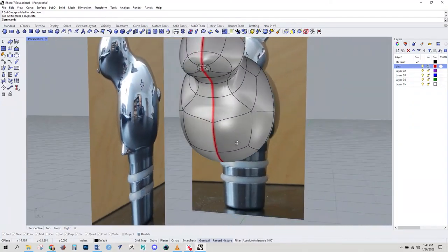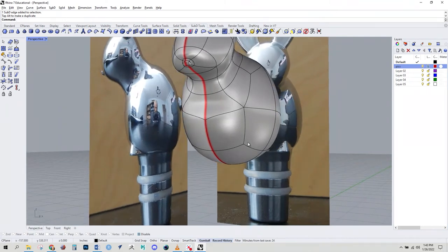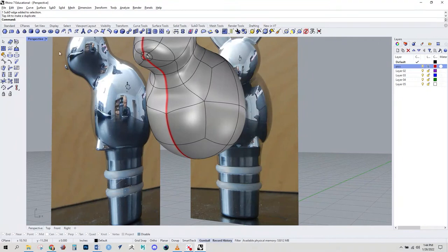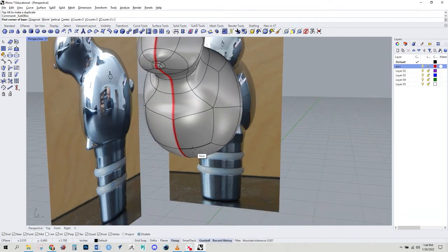I think I'm going to do these as a separate additional SUBD object instead of trying to extrude out, or instead of trying to bevel the mesh. I think that, based on some tests I was doing before, we're going to get some weird results because of trying to do this right next to the line of symmetry. So we will create a SUBD box. I'm going to hold Alt to snap right here.